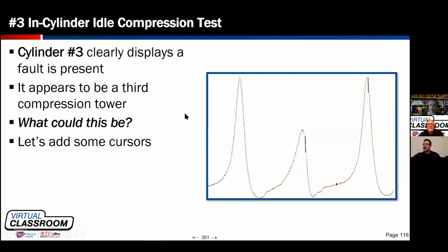So if I referenced an ignition strike that occurred right here, let's say I called this cylinder number 1. If the firing order was 1-5-3-6-2-4, ignition strikes, number 1 ignition strike occurs here, but number 1 intake stroke is 360 degrees later.